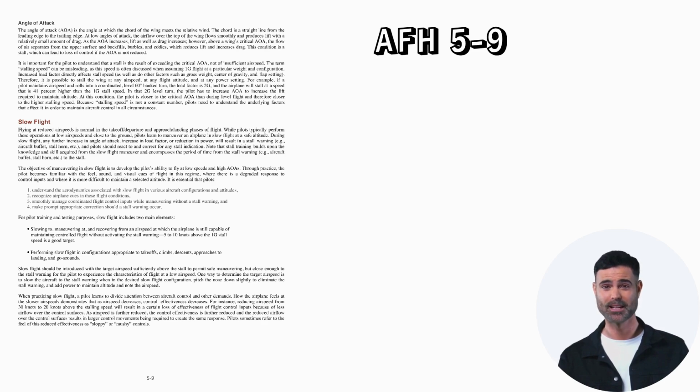For pilot training and testing purposes, slow flight includes two main elements: slowing to, maneuvering at, and recovering from an airspeed at which the airplane is still capable of maintaining controlled flight without activating the stall warning; 5 to 10 knots above the 1G stall speed is a good target. And performing slow flight in configurations appropriate to takeoffs, climbs, descents, approaches to landing, and go-arounds.